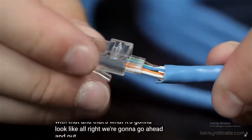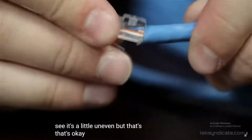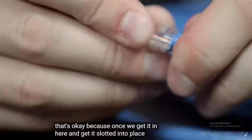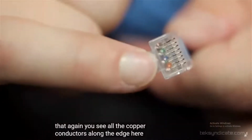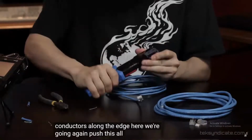Alright, we're going to go ahead and put this into the mod plug. You can see it's a little uneven, but that's okay, because once we get it in here and get it slotted into place, all these pieces, push it all the way in. You want to make sure that, again, you see all the copper conductors along the edge. Here, we're going to, again, push this all the way in. Double check the ends here.